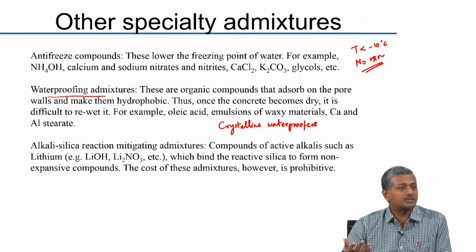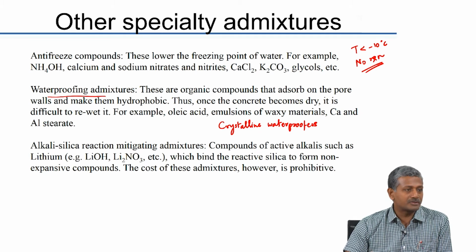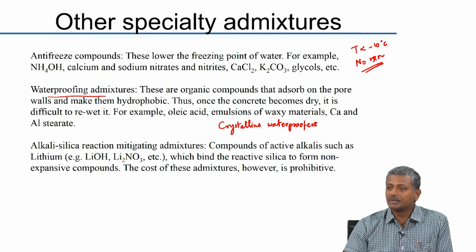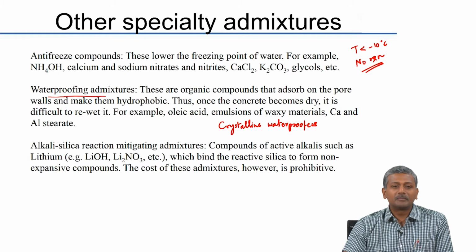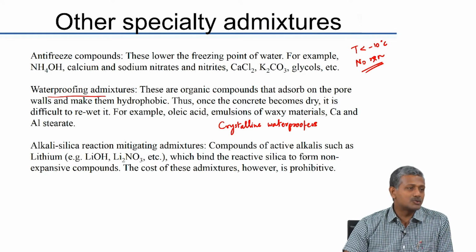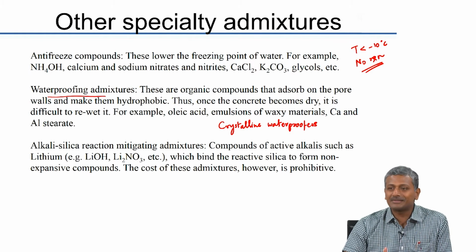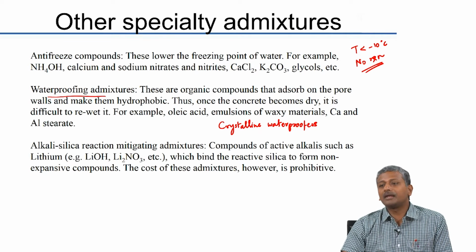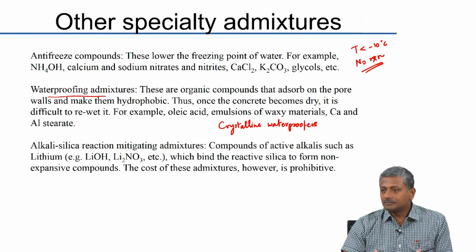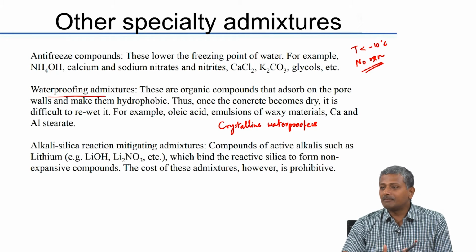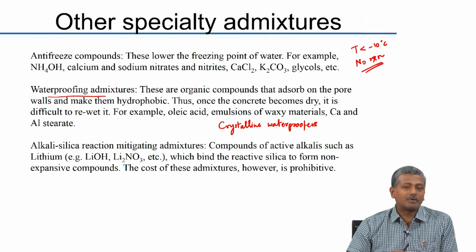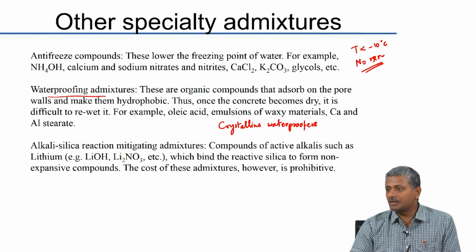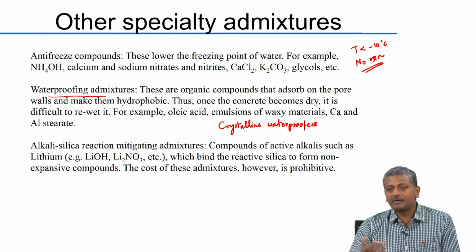As far as the literature supplied by the construction chemical manufacturer is concerned, it all shows excellent performance of these chemicals, but when we have tried to use these in our concretes, we have not really seen the same kind of effect as what is being claimed in the literature. So, we probably have to arrive at the correct mode of testing which can actually bring out the performance of these chemicals, because we have not been able to see it in our regular water penetration tests.